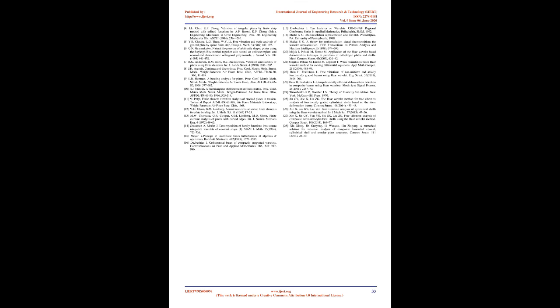4. Conclusions. In this paper, a reasonable analysis method based on the Haar wavelet has been presented to obtain the natural frequencies of rectangular plates with several boundary conditions. The basic principles and formulas of the Haar wavelet collocation method are described, and its approximation to displacement functions using HWDM is discussed in depth. The solution process of Haar wavelet used in free vibration analysis of rectangular plates is given in detail. The efficiency and accuracy of the presented method are proved for natural frequencies of rectangular plates with several boundary conditions.